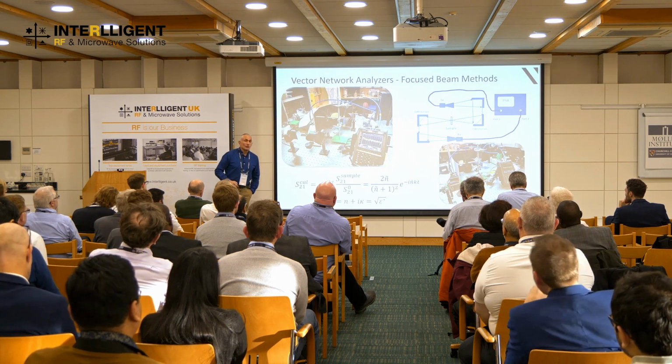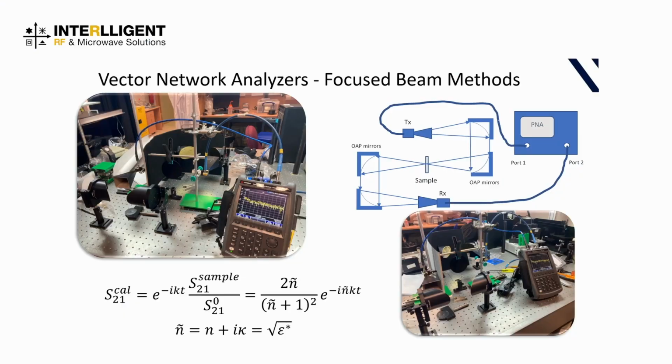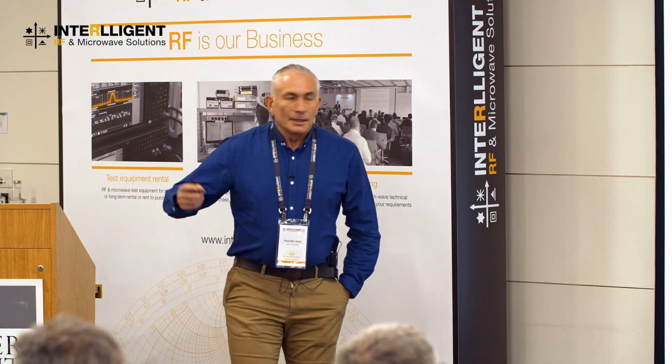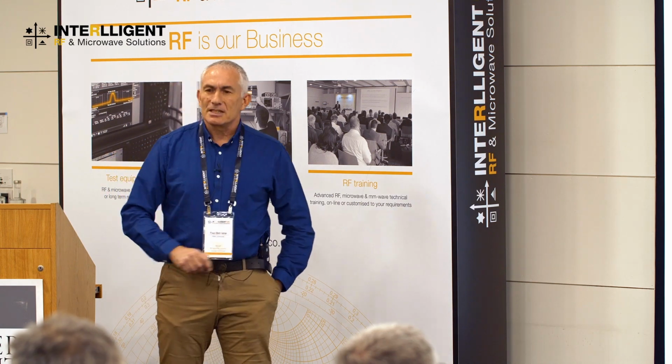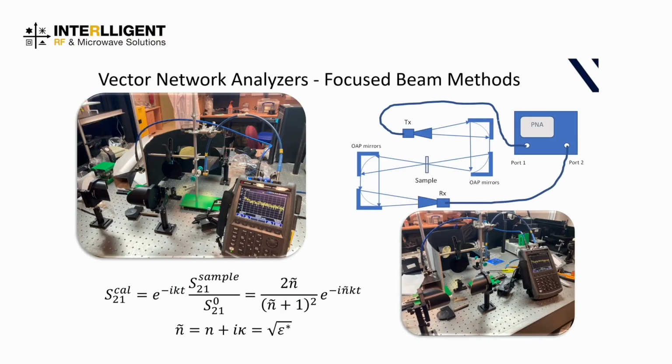And of course, you can use optical techniques. Now, you're going to use optical techniques when you start to go to higher frequencies, and suddenly you can't use lumped element approximations so easily. So this is, for instance, work done investigating, you can't see it very well, but there's a bit of very dark plastic there in the middle. And we're looking at the transmission through it because we want to get an idea of its absorption, because we want to use it for electromagnetic shielding.